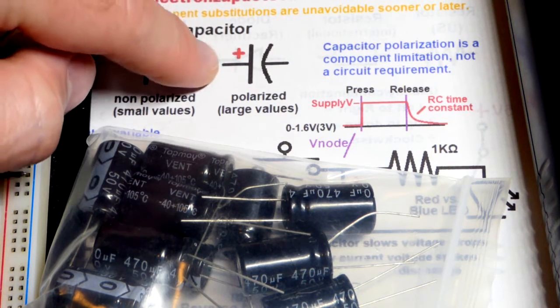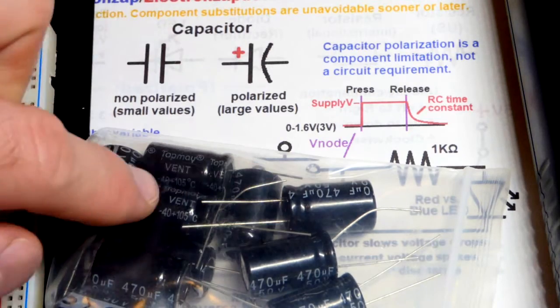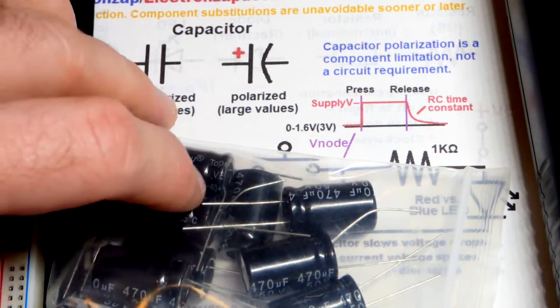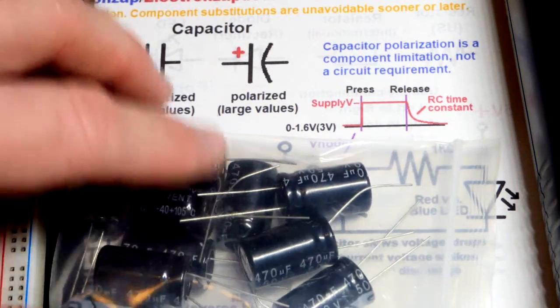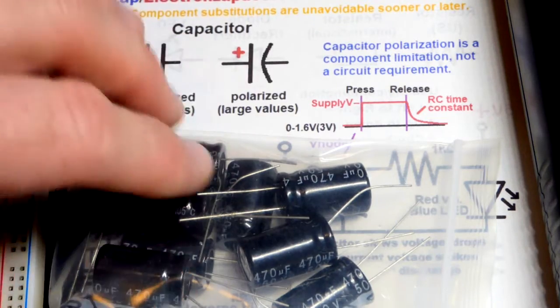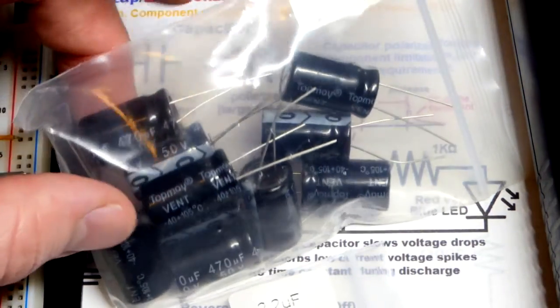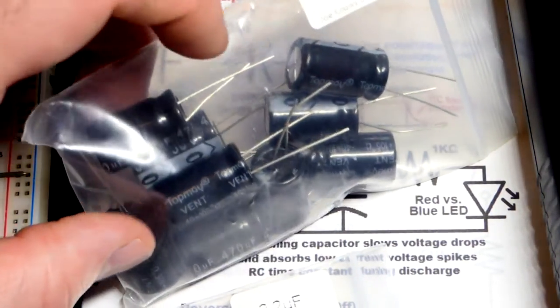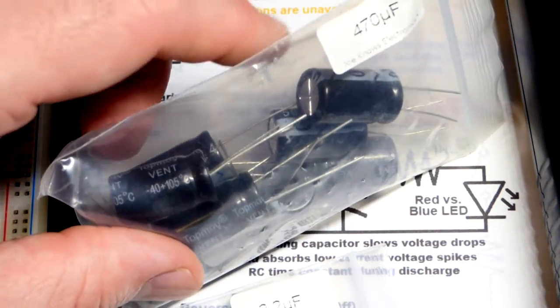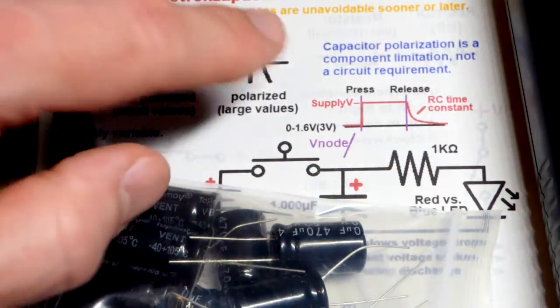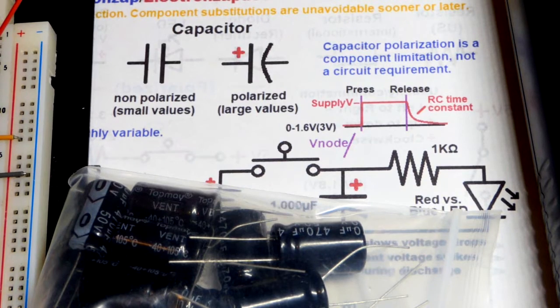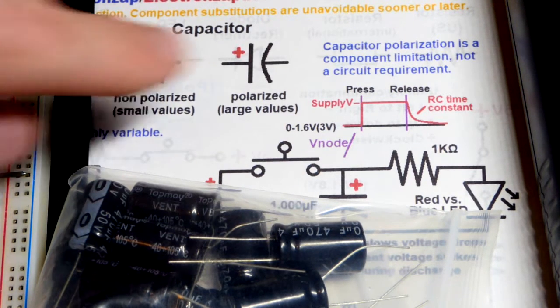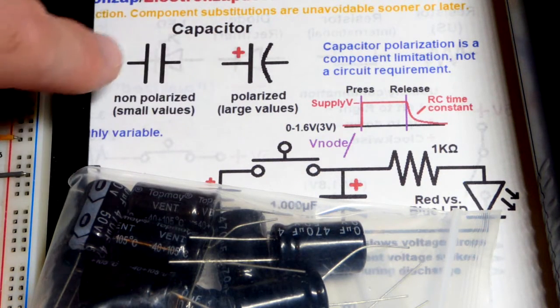So with the polarized capacitor, you have to charge the side that's labeled as more positive. In this case, it's not the labeled side. You have to attach that to the positive side of a power supply, and on the other side, you can see a dash. That indicates the negative. It also has a shorter lead than the positive side. That has to be more negative. And so you can discharge it to 0 volts, but you never want to reverse charge it.